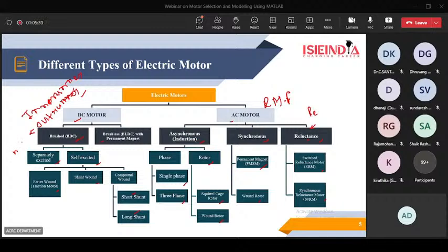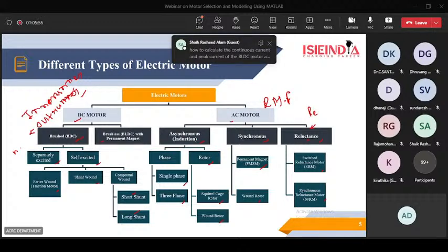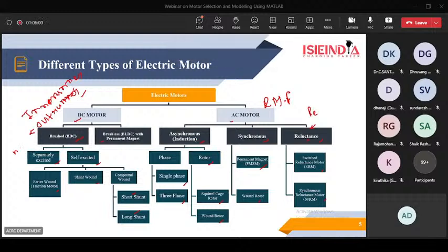We have seen some scooters, like e-vehicles, electric two-wheelers, like we talk about the Ola and the Ather. In the Ola S1 they use the hub motor. In a hub motor the rim is replaced by the hub motor itself, the outer part itself is the rotor, then the tire is placed upon that. According to that the BLDC motor rotates.